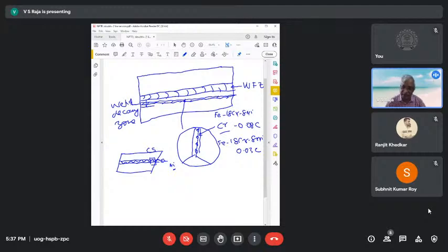Now assume the paint coating has gone away because of some reason, maybe mechanical damage. Now the zinc coating is exposed. Should the zinc coating prevent galvanic corrosion through sacrificial action? No. It is going to act the same way it would act had the steel been coated with plain zinc. So zinc is not going to help at all once the paint coating is gone.